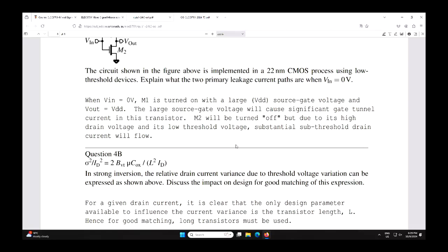Then to retain the same current, you need more gate source voltage. So the gate source voltage will have to change. So that's a dependent variable now, the gate source voltage, which is a good way to think about it during the design phase and when you decide how things are. It's not necessarily a good thing to think about it when you hook a voltage up to a transistor, because that's your control variable.